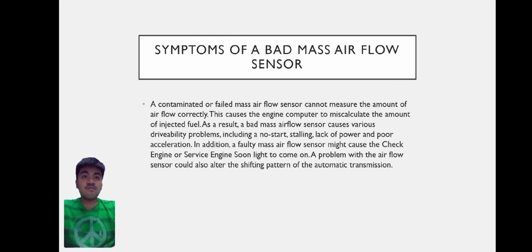Symptoms of a bad mass airflow sensor. A contaminated or failed mass airflow sensor cannot measure the amount of airflow correctly. This causes the engine computer to miscalculate the amount of injected fuel. As a result, a bad mass airflow sensor causes various drivability problems, including no start, stalling, and lack of power and poor acceleration.